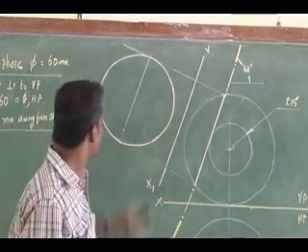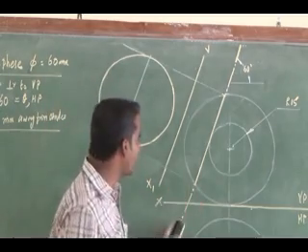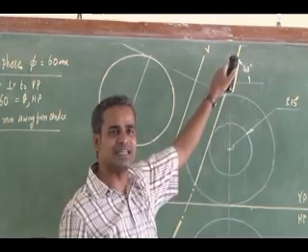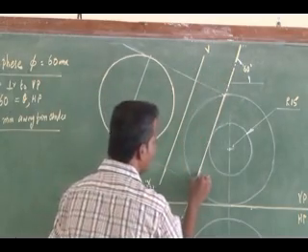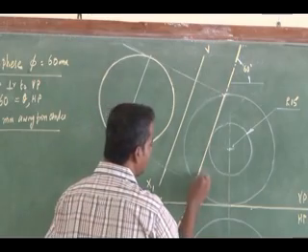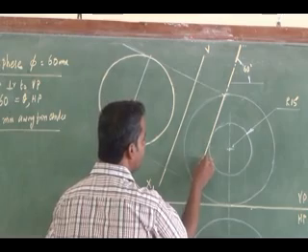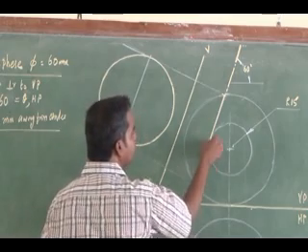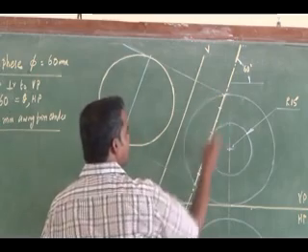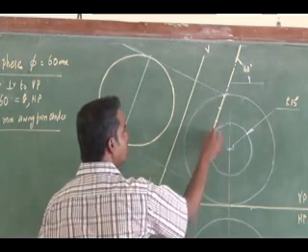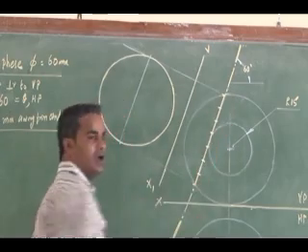Otherwise, what you can do is mark the cutting points on the cutting plane wherever it passes through the sphere. I can mark some finite locations for my cutting points on the cutting plane, any arbitrary locations or finite distances.